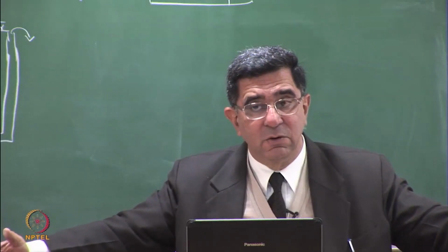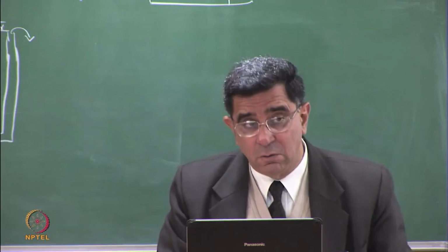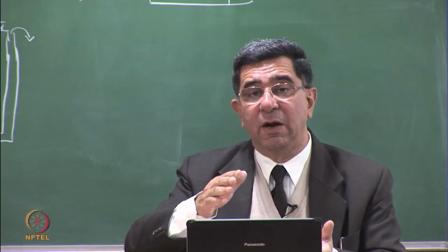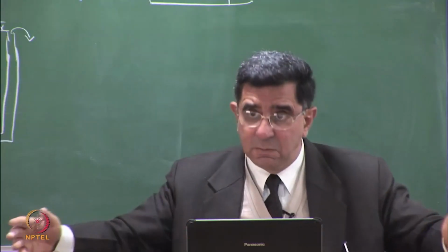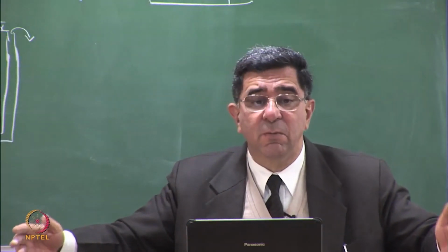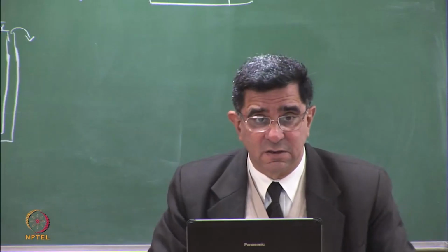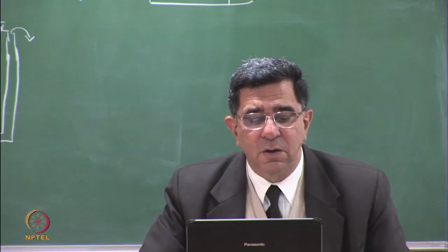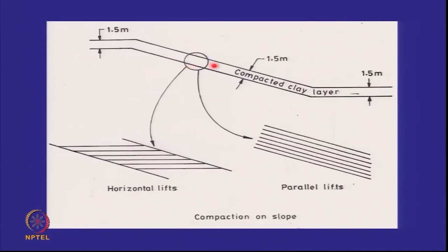right? Well, do remember, first you have to use smaller rollers, but this is 1 meter thick. If you look at a 3:1 slope, this will become 2 or 3 or 3.5 meters wide in a horizontal sense. The thickness when we talk about is normal to the slope. So this is, when you cut it horizontally, will have a much wider thickness, and it is possible to do this compaction.